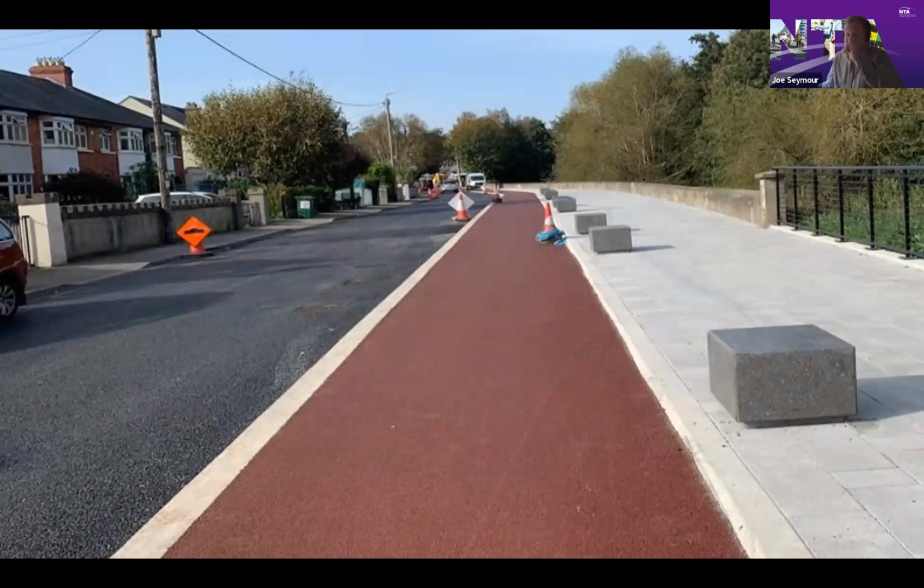Here's another example of red put in September along the Dodder in the South Dublin County Council area, and you can see the significant difference that it highlights between the cycle lane and the footway. And this is based on the new specification, so it has the smaller stones, so it's really level and smooth for cyclists to travel along. And you can see quite a strong color with the mix. We're also trialing forgiving curbs on this one, which you can just about see here, which we'll be working on over the next while.